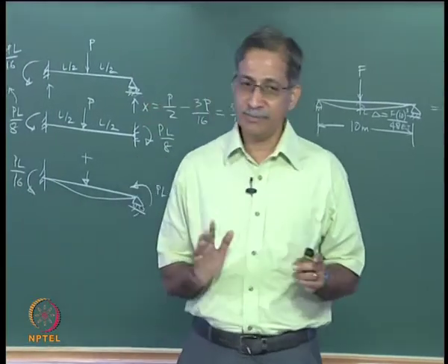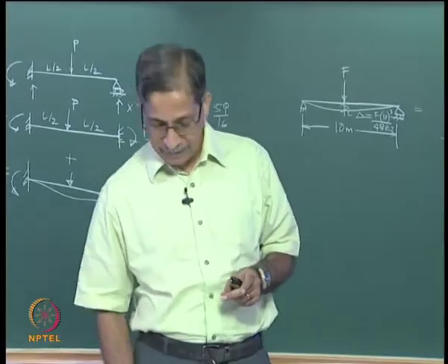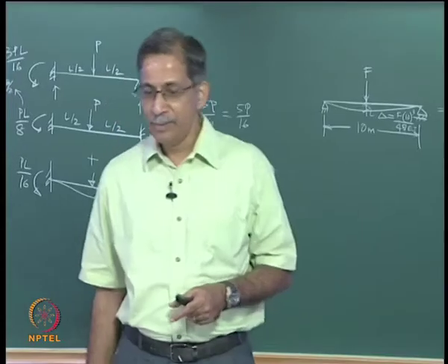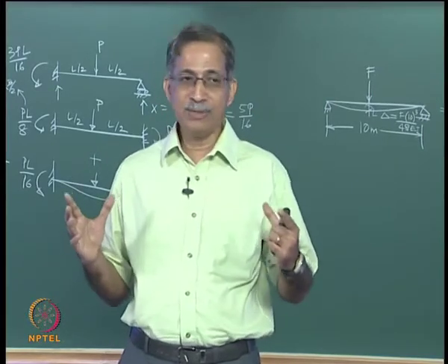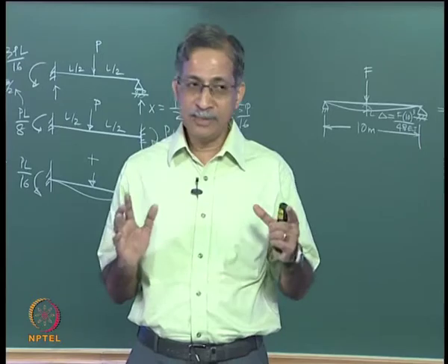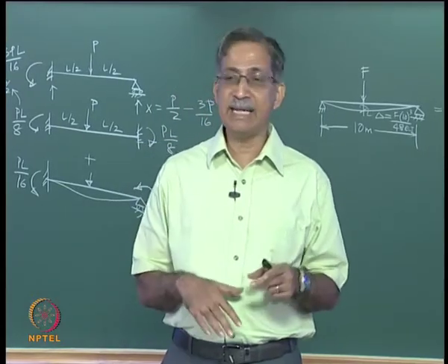It works if your frames are all symmetric, but that would mean that your end frame, the last one, would take half the load compared to an intermediate frame. Do you think that is the way it is going to behave? Why not? Well, in reality that whole building is going to move as a whole. It moves as a whole because of the slabs being integrally present there.